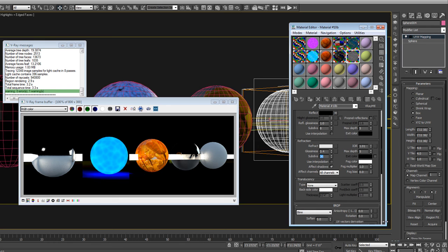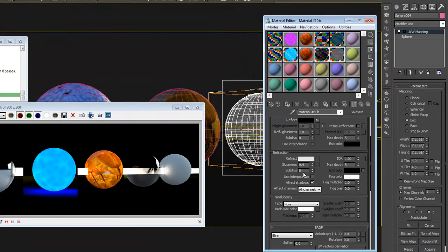Like, in actuality, to make a nice rendering, you want to put this maybe around something like 30. One other option is to use interpolation, which speeds things up significantly but makes it look pretty blotchy. But you can turn on interpolation and turn this up to more like 30 or something, and that's still going to be faster than if you had interpolation turned off and you were rendering it at 8. And I don't know if it'll be faster, but the quality compared to the speed will be a lot better.